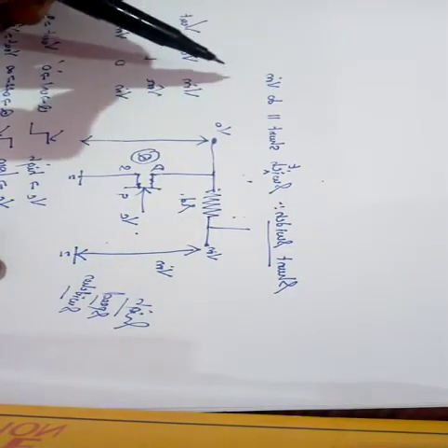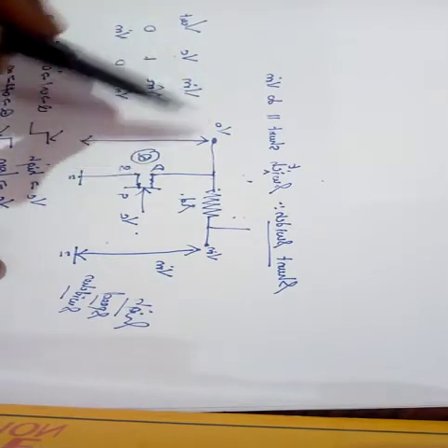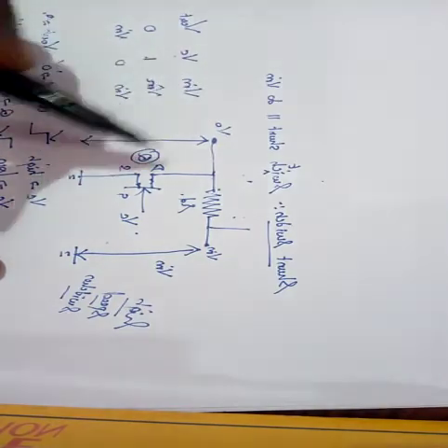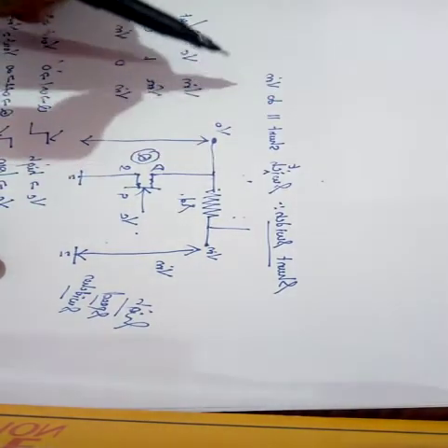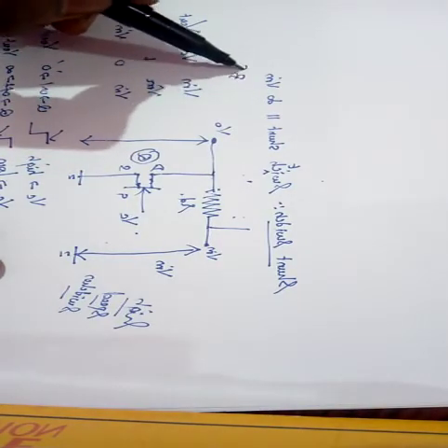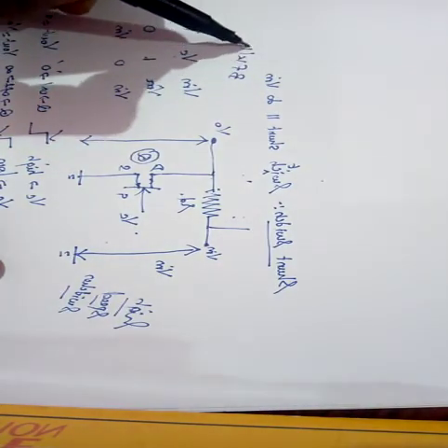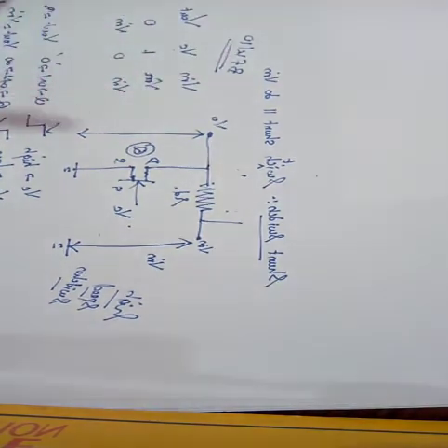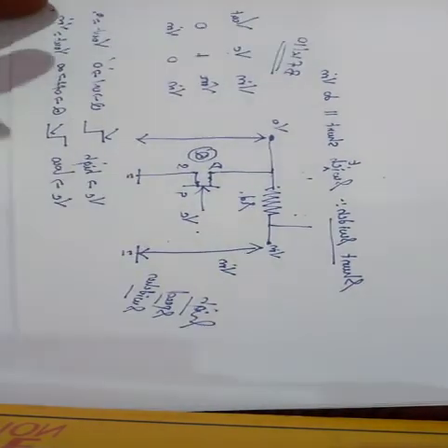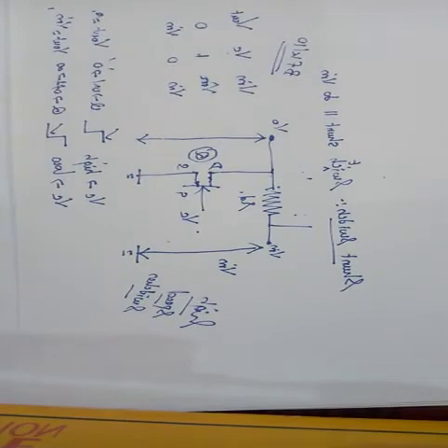Even when you try it in the laboratory, to visualize a better output you can use a JFET called BFW10. It is a high frequency junction field effect transistor, which you can use while testing the circuit in your laboratory.